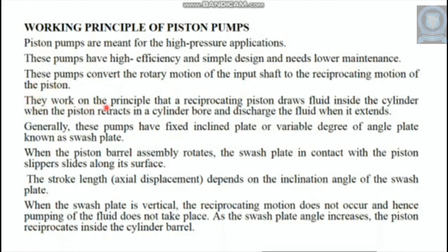They work on the principle that a reciprocating piston draws fluid inside the cylinder when the piston retracts in a cylinder bore and discharges the fluid when it extends. Generally, these pumps have a fixed inclined plate or a variable degree of angle plate known as a swash plate. When the piston barrel assembly rotates, the swash plate in contact with the piston slides along its surface.